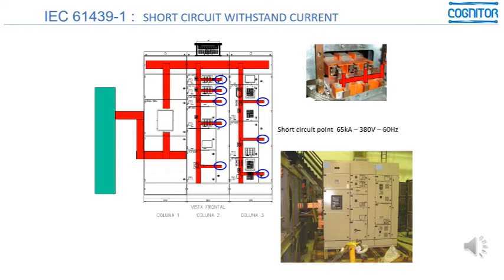And there are two purposes in this test. One of them is to check if the bus bars are able to support the very high short circuit force that will occur inside the switchgear, because here we are speaking of levels of current around 65 kA, 8 kA, 100 kA, in bus bars which are separated by very small distance, so the forces involved are very high.